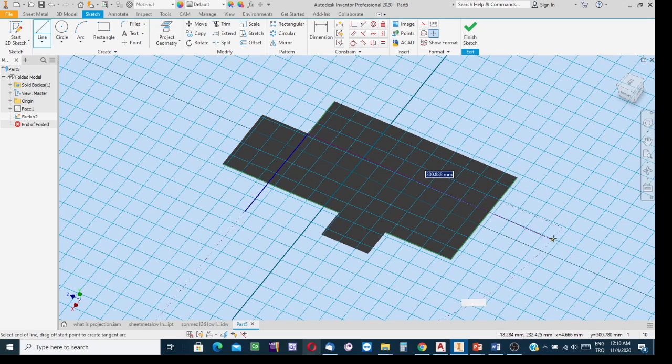If you couldn't perceive the angle, I created this boundary as inclined with a further extension, then apply parallelism constraints to say that this projected edge and this sketch are parallel. So you see I had this sketch line in the correct orientation.